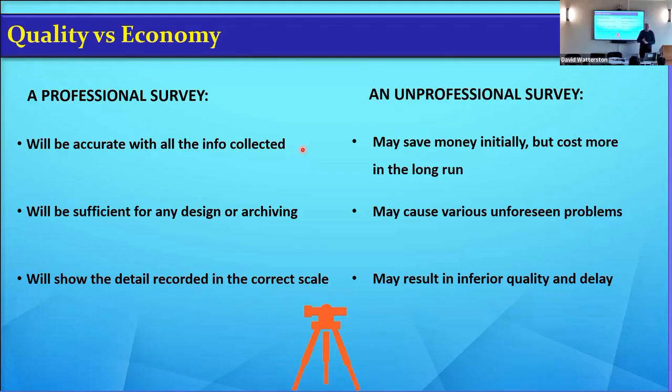As I say, Google Maps is pretty good for giving me an overall view, but you can also get the Pro Map, to go and get the Ordnance Survey digital data, which is the whole country mapped, and it is getting better and better and better. Whereas the old days used to be working at 2, 3, 4 feet accuracy at 1250 scale. It's now getting down to 50 or 100 mil. So it's actually quite good. So you can get a Pro Map for about 20, 30, 40 quid, digital data.